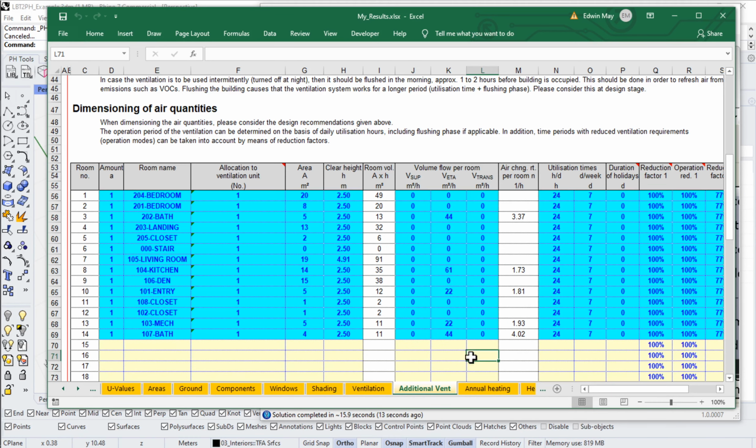So we are no longer taking our flow rates from the Honeybee programs or the Energy Plus method. We are using our explicit cascade ventilation approach here to configure exactly the amount of airflow that we want in the different spaces. Notice here I'm pulling air out of some spaces. I have not yet set up any supply.